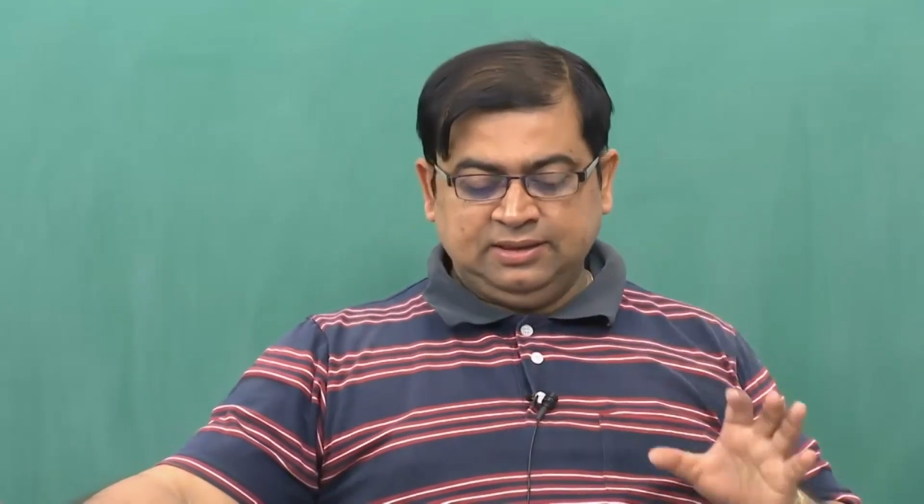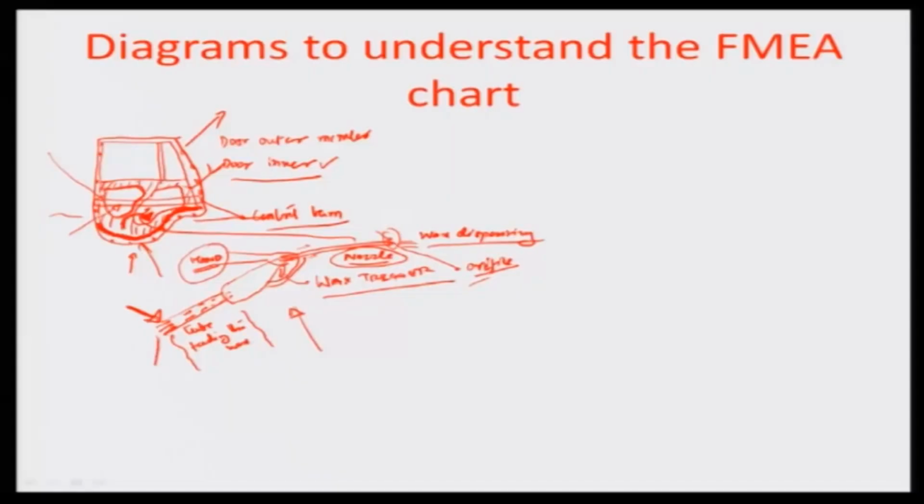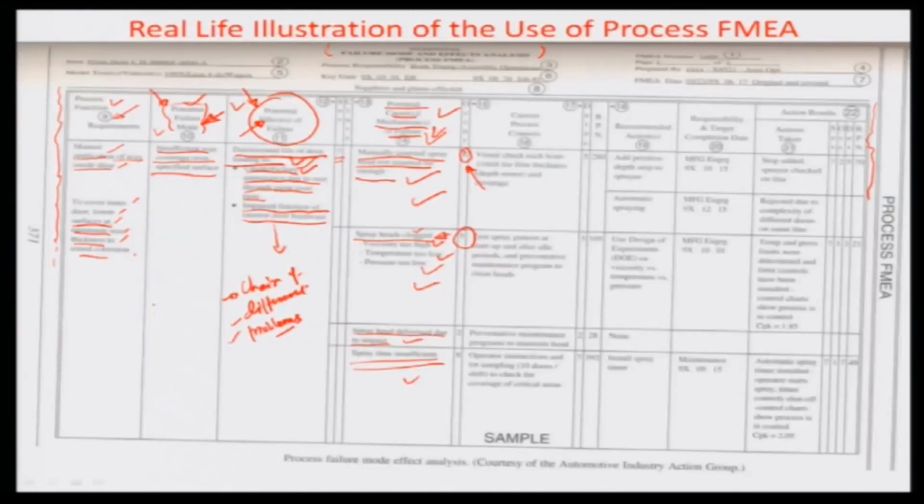Also it has to be done at a certain temperature condition, and maybe because of non-compliance of those temperature and viscosity conditions, the wax which is coming into the nozzle may not be melted to the level that it is supposed to be, and it starts clogging the nozzle. So there is about 50% occurrence, and so the engineer rates that to be about 5.